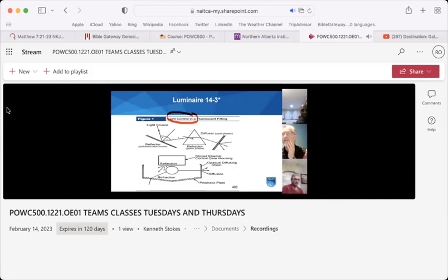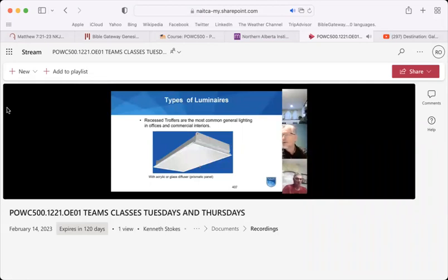Here's the light control methods in a fluorescent fitting. So we have some kind of light source. We can have reflectors, and the light will bounce off a reflector and go in a different direction. Sometimes it's refracted. Sometimes it's also diffused, and we'll look at the different parts that do these things. So here's our source of light. It's being reflected and refracted, with the intent purpose of spreading it around the room. In most cases, we have general area lighting. We want this light to go all over the place, all around, all the different directions. And sometimes we're going to concentrate the light for spot lighting. So we're just going to put light exactly where we need it.